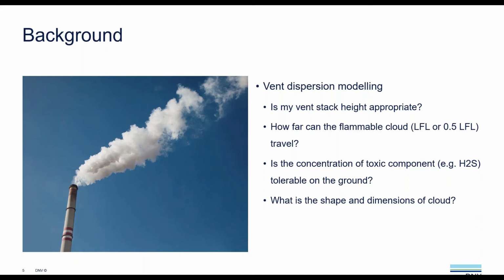How far will my flammable cloud travel? Will it be able to reach an area of ignition, which then leads to an ignition of the cloud, and this will then give off radiation or explosion effects. If there are toxic components in my gas mixture, then I need to consider whether the concentration of the toxic component, for example hydrogen sulfide, will be tolerable at the ground level where most of our population is located. And lastly, we might want to consider what is the shape and the size of the cloud.